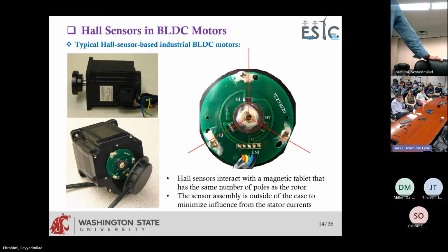Yes, because Ninad and everyone else was also saying something about linear control. I'm used to the induction motor control where you use vector control, and even for the synchronous machines we use vector control and sensorless control. And here you are taking advantage of the basic torque equation itself and the detection of the torque. So in this case, going sensorless is solely dependent on the torque, and you're using a lot of estimation methods on the basis of measurement.